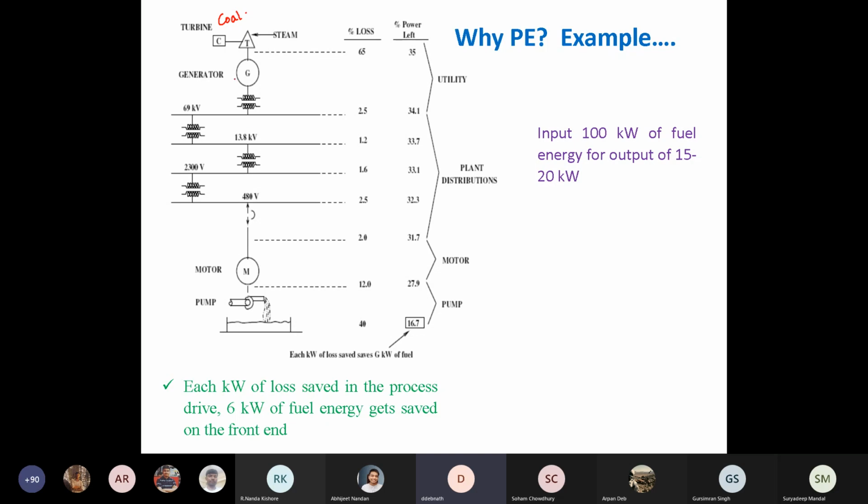Using that, you'll be rotating a generator that will produce electricity. Then that will be stepped up, and after the transmission network, it will be stepped down again. Finally, you will get in your home 230 volt for different uses, 230 volt single phase or 3-phase 415 or 400.